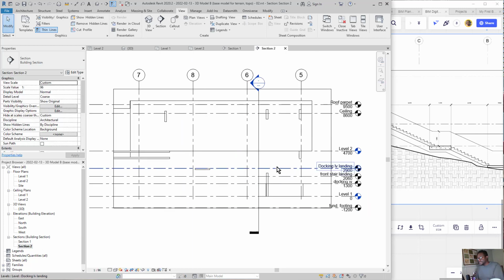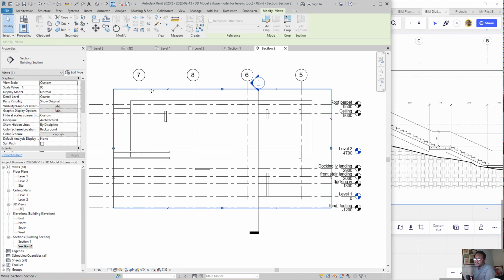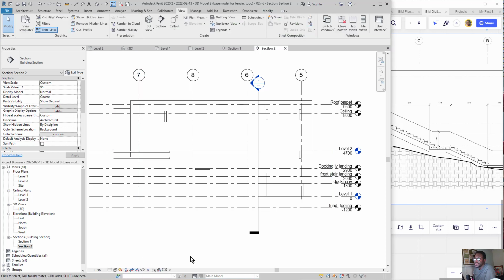Now you might notice that we can clean this up a little. For example, we can hide this boundary wall by clicking the hide button here. So we're going to hide that. And then we see all of these levels here. Now you are going to see all the levels we created, and you can see that I created some additional levels to help me out.